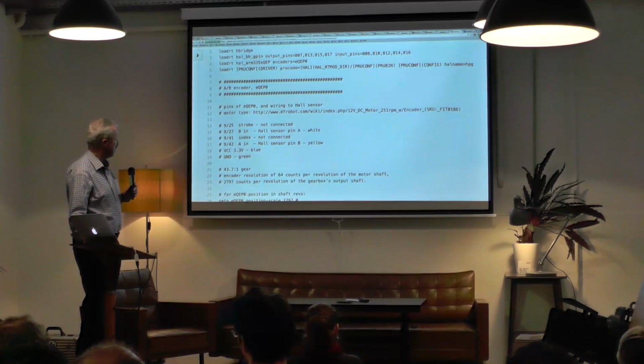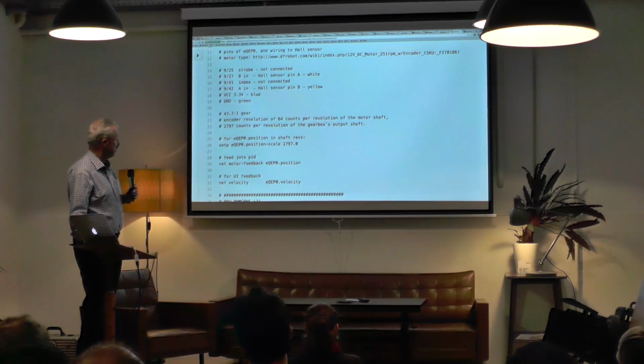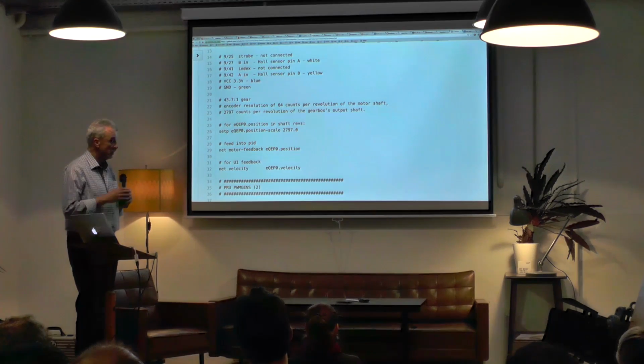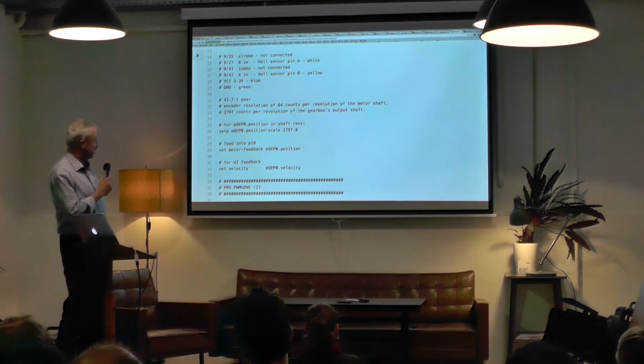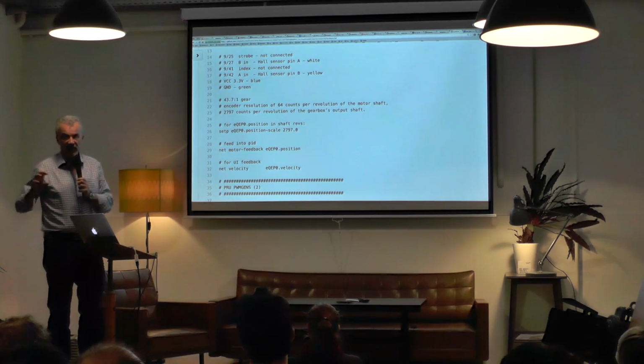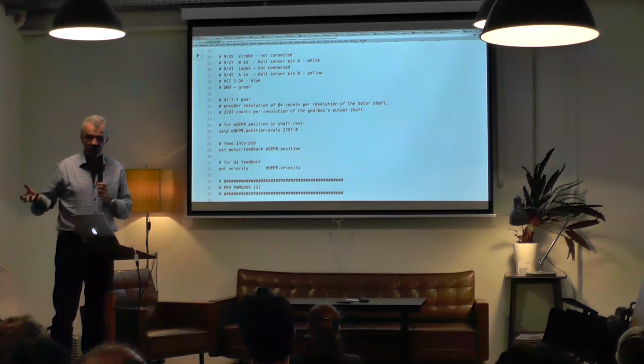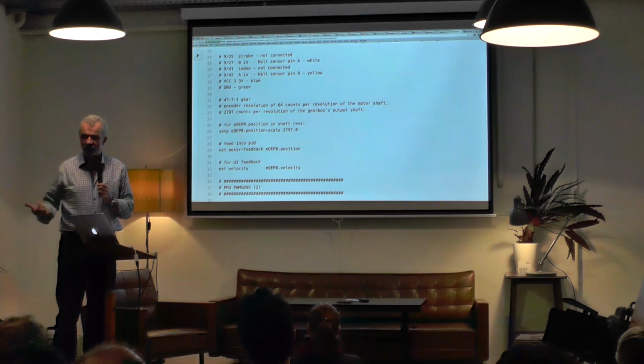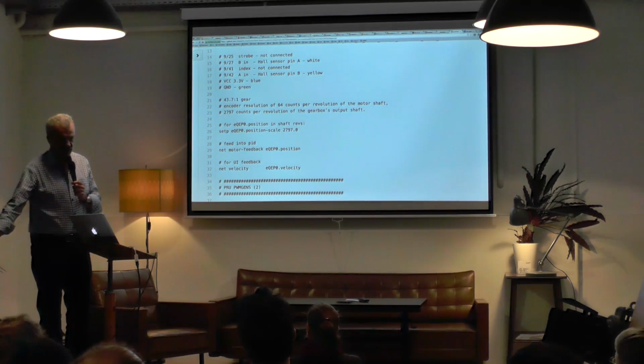So that's the fourth driver, which is loaded here. For instance, a part of the configuration of the quadrature encoder is the relation of the number of counts of the encoder for one turn of the axis to revolutions. Now that is a geared motor.